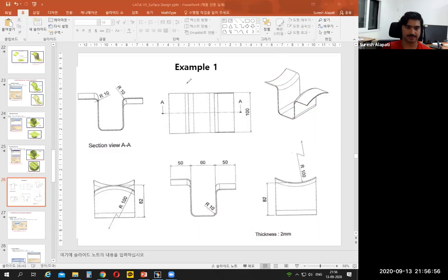So first you create this one. Create this sketch and extrude, length is 100. I created this sketch, that is the front view, and the extrude is this one, that is 100. You can create this with whatever length, but the minimum length should be around 82. Later you can delete that portion, the upper portion. Trim the upper portion.